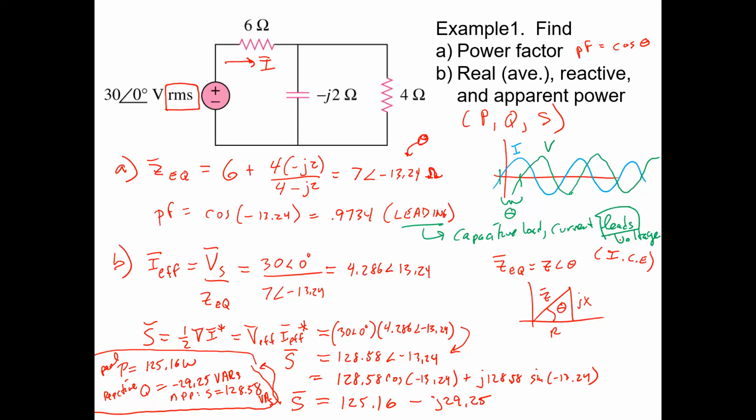And as we worked out in the lab yesterday, when we had a negative impedance angle, you actually got a positive angle for your current phase. Your theta I was greater than 0. And so that gave you a theta V minus theta I of negative. Yeah, it ties together from that. That lab is actually really useful.